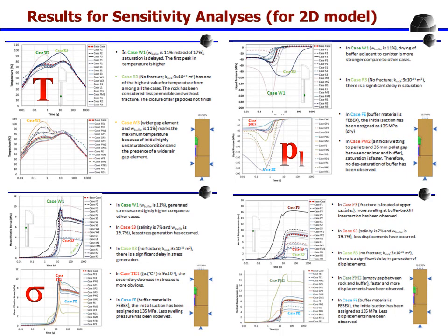The results for the sensitivity analysis are very important for the performance assessment studies. In this case, you see that temperature, liquid pressure, and stress are highly sensitive to, for instance, the presence of fractures, properties of the rock, presence of gaps, whether the gaps are empty or are backfilled with pellet materials. So different engineering-related aspects that can change from one zone to another, and even in the same repository.